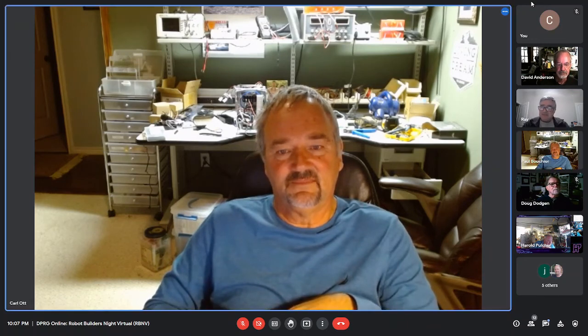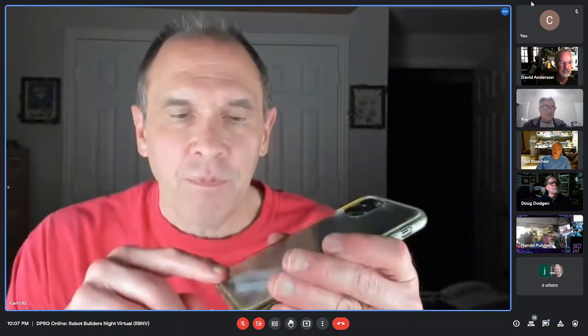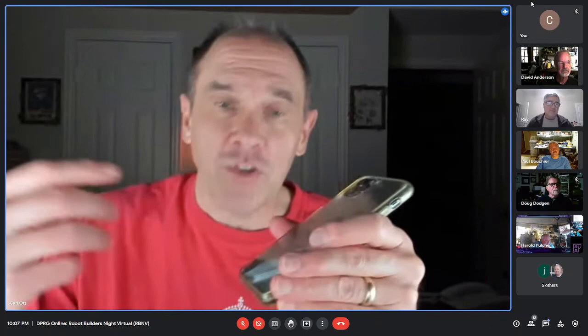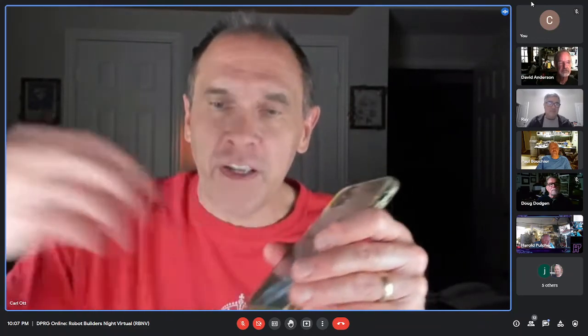I don't know exactly how it's done in the phones, but it must be similar because the phone just won't work if it doesn't have enough charge. And part of that is because to get the maximum power out of the cellular antenna, it's more power than you can get off your typical charging circuit. So you have to have enough energy in the battery so that even if you're using the phone while it's charging, the battery can take care of the instantaneous bursts from the RF power amplifier. So it's drawing current from both the battery and the charging circuit to operate at certain parts.